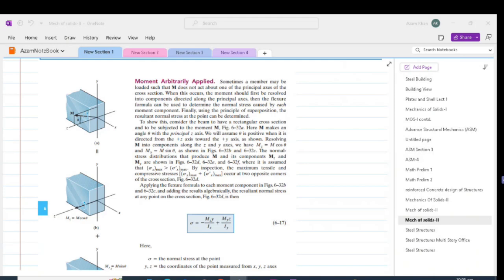We are now ready to discuss in further detail the unsymmetrical bending. The unsymmetrical bending is defined as the bending caused by loads that are inclined to the principal planes of bending. One of the examples which we previously quoted was of a roof purlin, which, because of its inclination with the roof, is subjected to loads whose planes make angles with the principal axis of inertia of a section.